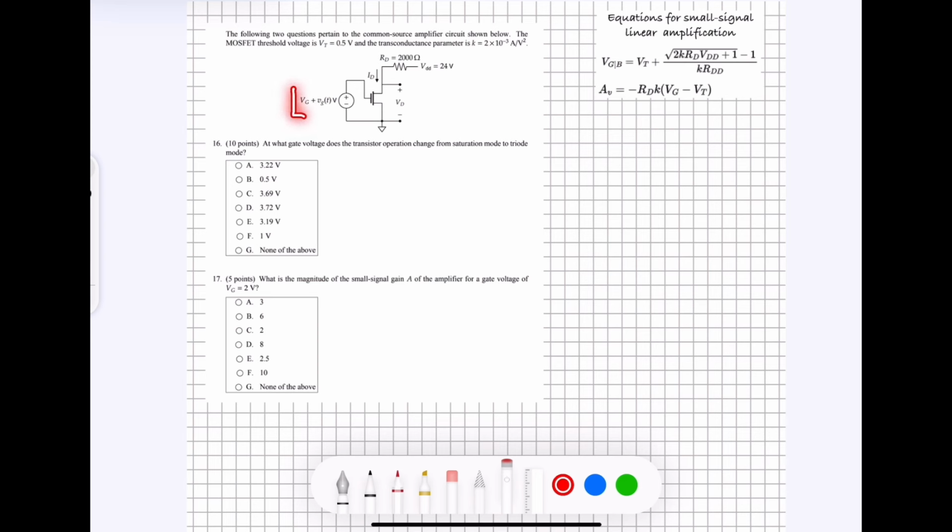And also this over here, if we look at the voltage source, it has two parts in it, one with the uppercase V and one with the lowercase v. And this uppercase V is going to be like the DC voltage. But this kind of voltage source also has an AC component to it. So when you have these two components, that's going to be a giveaway that we're using a linear amplification. And that's the kind of circuit that we're doing right here.